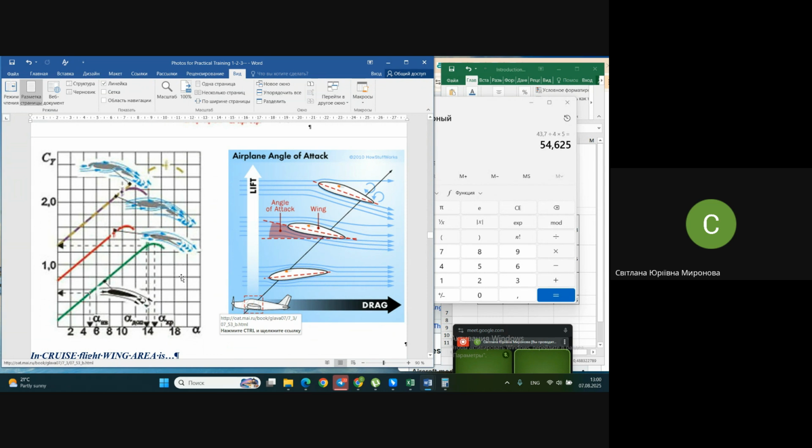Typically, it's considered that a non-flexible wing made of metal, I mean, for a modern passenger airplane with rather big payload, rather big, meaning more than one passenger at least. Wings are significantly stiffer and made of metal usually, or composite materials in modern conditions, and they are considered non-flexible wings. For non-flexible wings in cruise flight, it's around 1. Also with variations, but for takeoff and landing using high lift devices, it's maybe 0.6 up to 2, or even a bit greater.